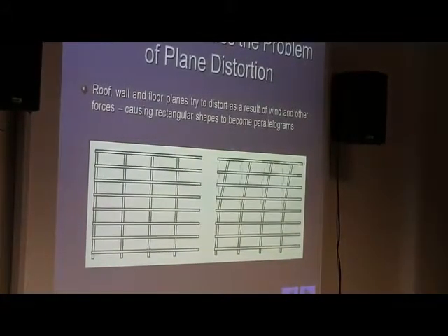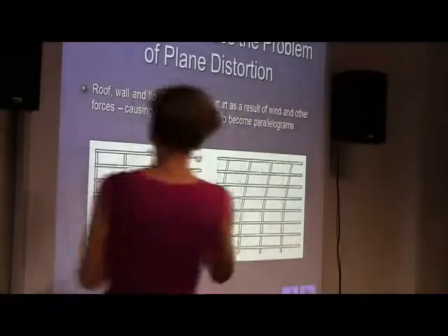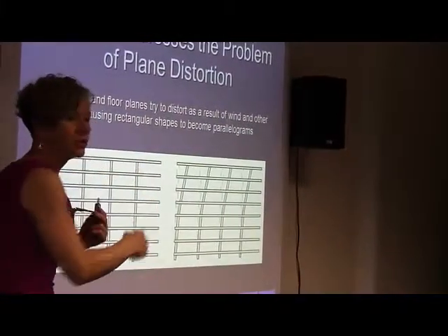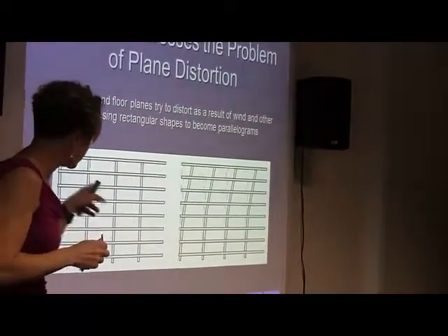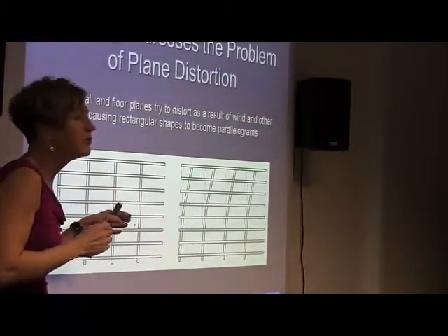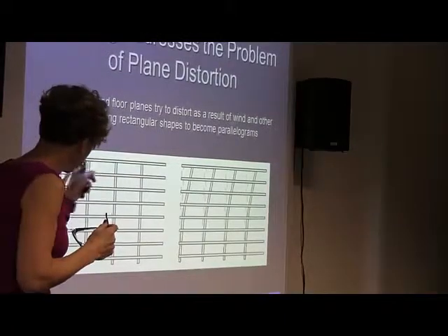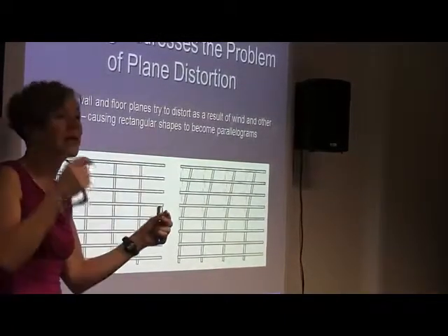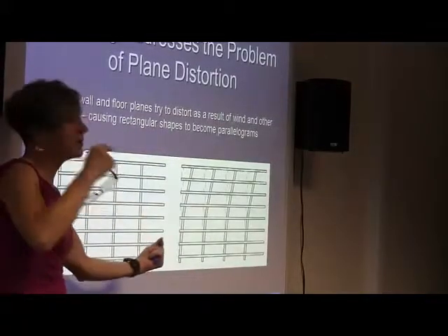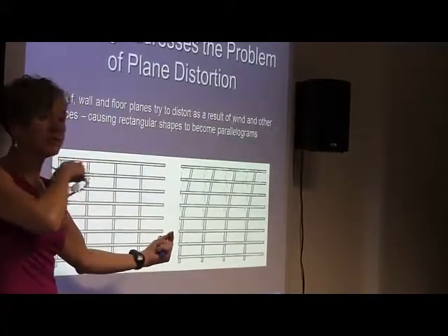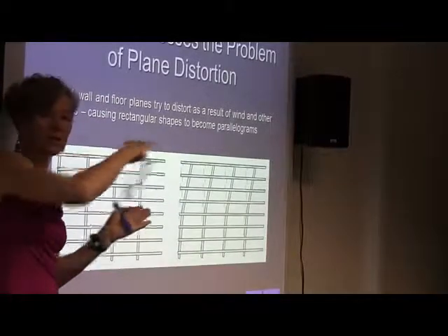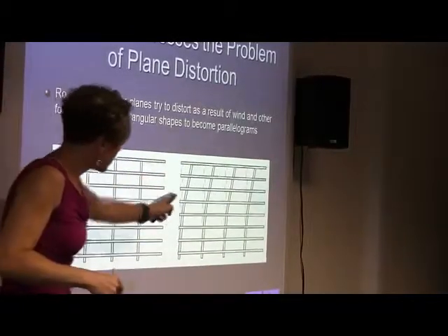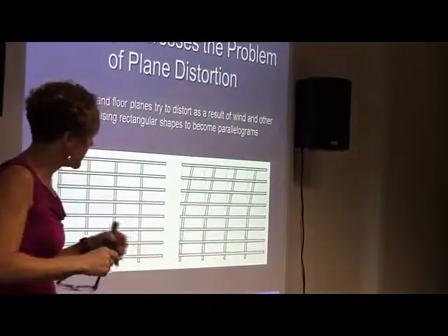So if you imagine this sort of structure connected with nails, a nail at each joint, you'd expect that structure to be quite stiff, but if you have a single nail at each of those joints, you know that that sort of structure with rectangles, if you hold the bottom of it and put a force up on the top left-hand corner here, it just folds up, doesn't it? So that kind of situation happens quite easily.